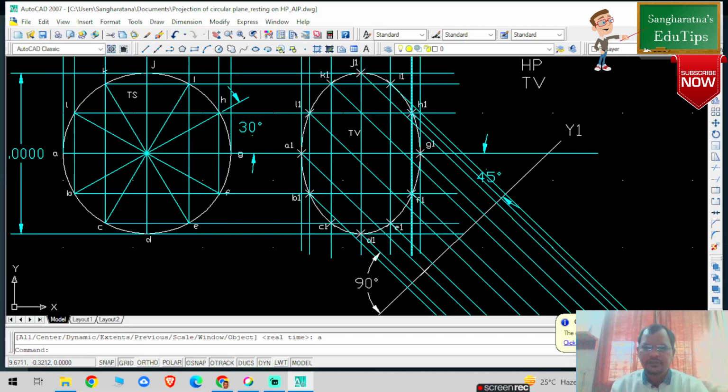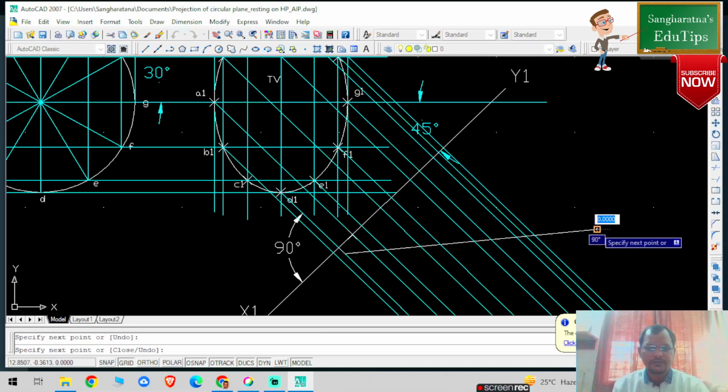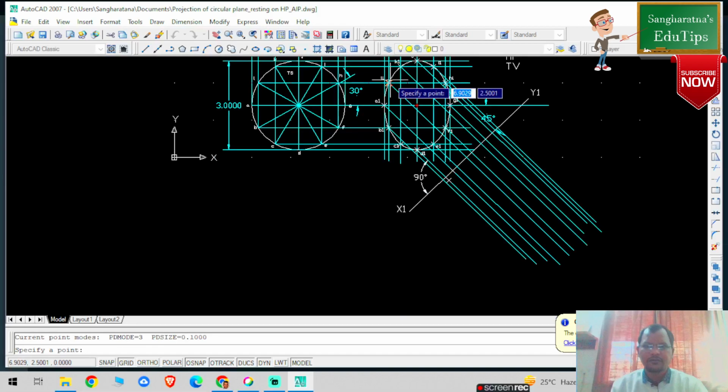where is my B? This is my B. From this particular point I'm going to draw one straight line, of how much? 0.1421, and press tab, then 45 degrees. So this is my another point, you can check, press escape, so you can delete this. Similarly from B dash L dash, press escape, Z enter, A enter,